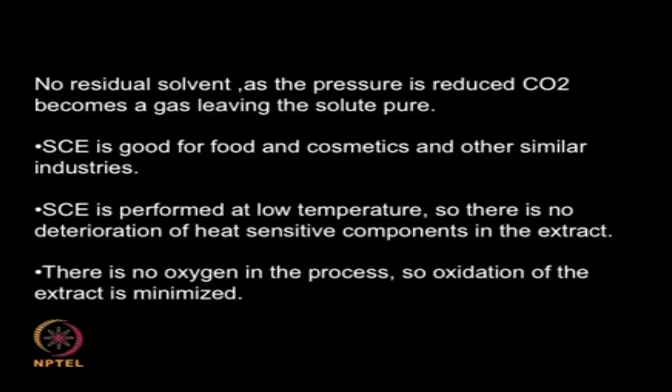Main advantage here is I can reduce the pressure and convert the supercritical carbon dioxide into the gas, so there is no residual solvent left behind with the solute, so the solute will be 100% pure. So it is good for food and cosmetics and other similar industries.